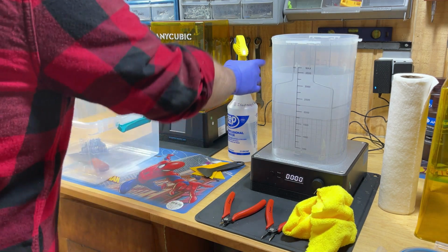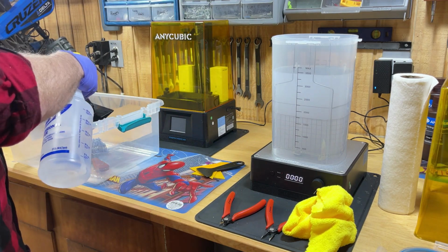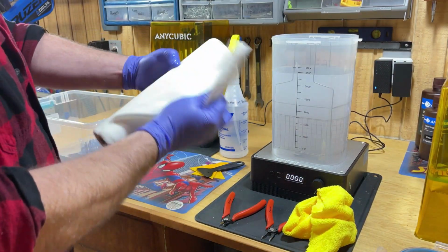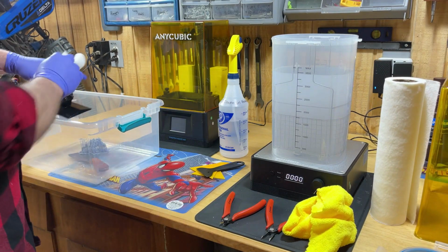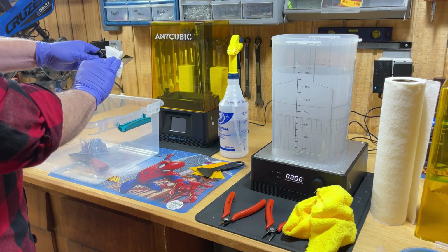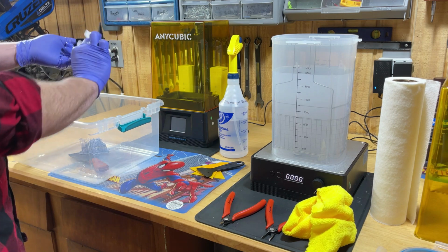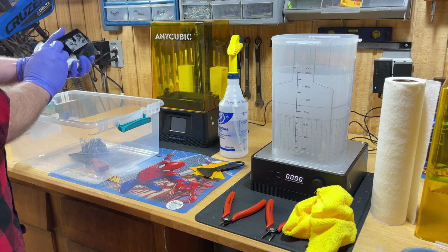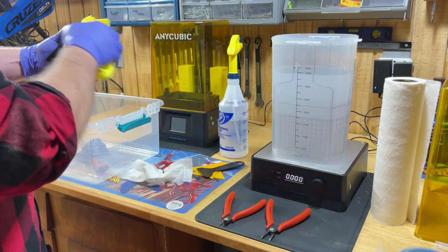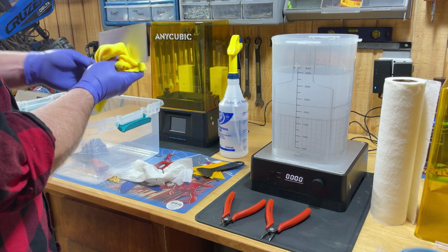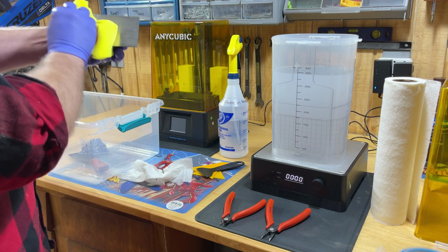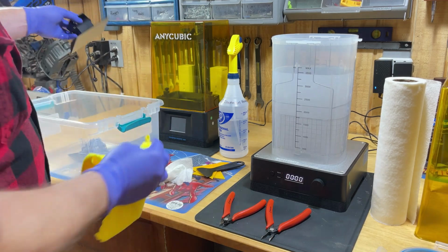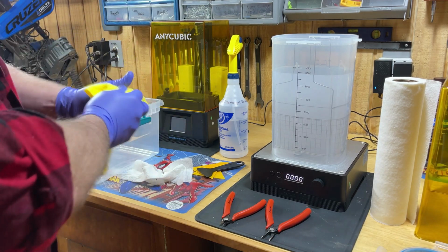So once we got the plate off, I'll give it a little squirt down. Clean it up a little bit. Because there'll be excess resin on top. You want to get all that off there. Once the majority of it's cleaned up, give it a little microfiber, because those paper towels leave fuzzies behind. And clean the build plate part real good. And we'll just set that off to the side, put back on the machine when we're done,